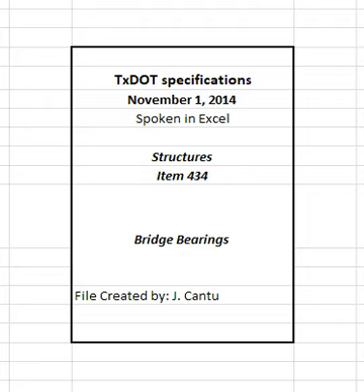Otherwise, provide connectivity between the top plate and the sole plate or grouted interface as indicated on the plans. Coordinate any necessary adjustments to the sole plate geometry, connection method, or grouted interface with the engineer to ensure compatibility with the structural design, before ordering any materials. Provide bolted connections for connection to steel trapezoidal box girder superstructures. 2.3.3.2.2 Stainless steel. Provide Type 304 stainless steel sheet in accordance with ASTM A240. The thickness must be at least 1/16 inches unless otherwise shown on the plans.